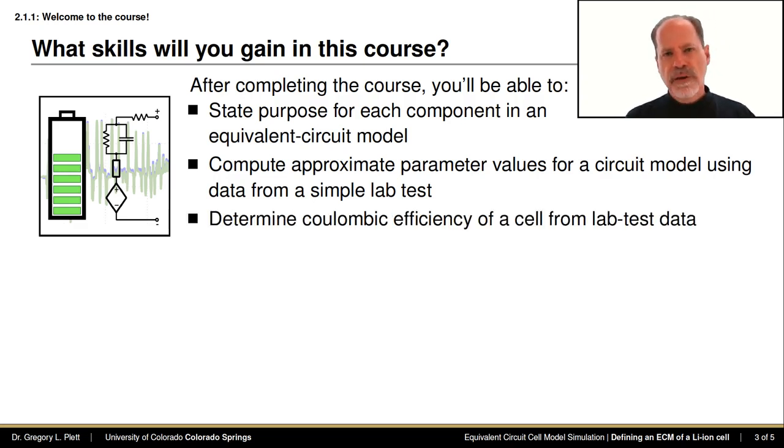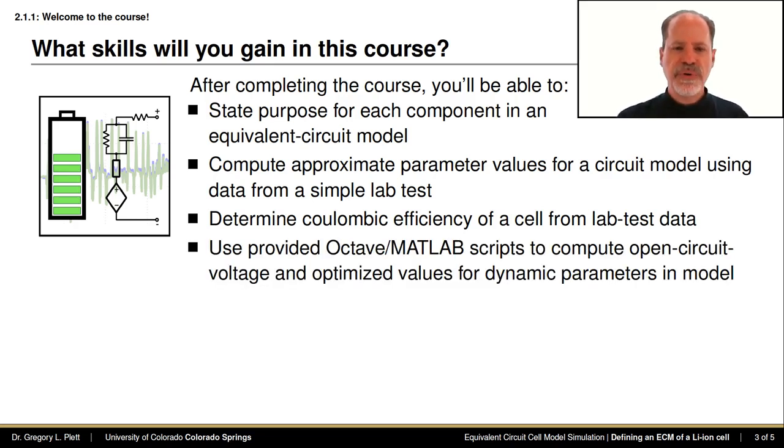And going a little bit more in depth, you will also be able to compute more exact estimates of coulombic efficiency of the cell and total capacity of the cell from lab test data. You'll be able to use the provided computer programs to compute open circuit voltage and optimized values for all of the cell model parameter values.